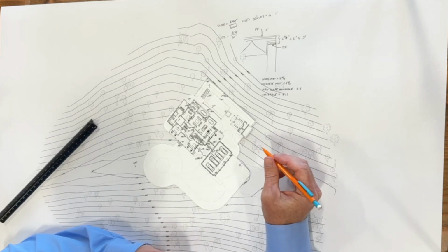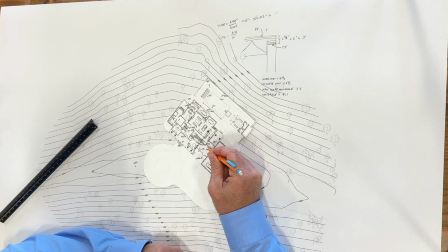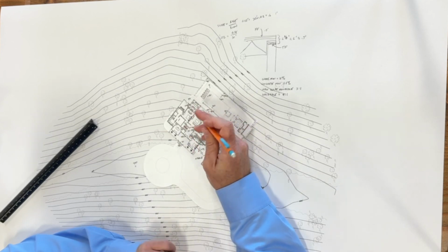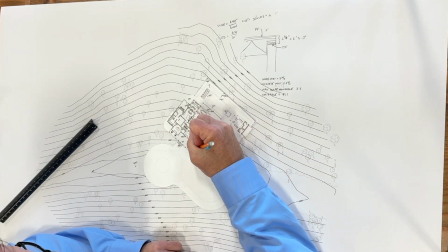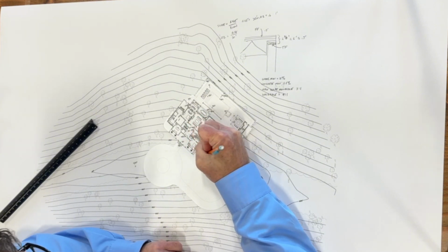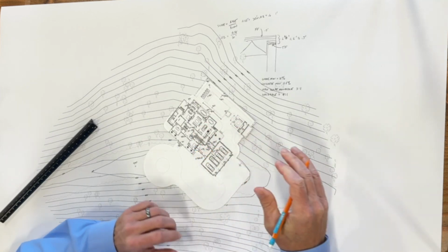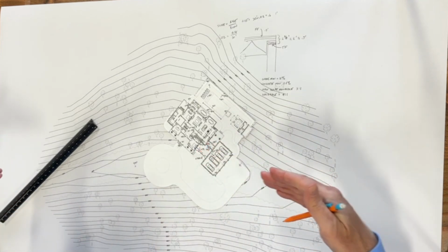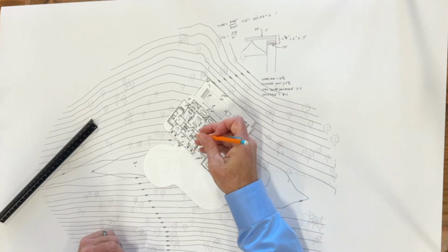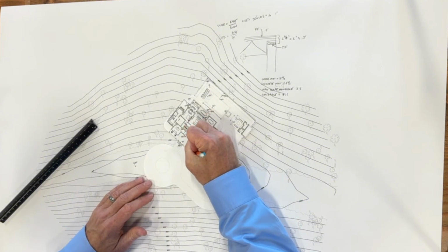So that sets that. So now we know this is a 940.5 and that's a 941.5, right? That means the 941 comes through right here, right? That contour line. So now I'm going to make that contour line go like this. And notice I put these little hooks on it, right? The contour line. What that means is that little hook shows that the water is sloping away from the building. You don't want the water to be running straight next to the building because then it can go back in. So this little hook indicates that it's sloping this way. The water is actually going like this.